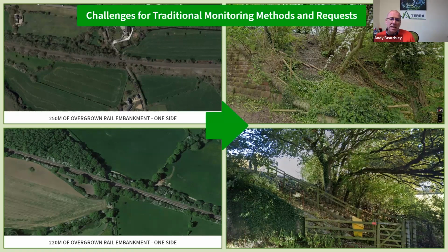In many situations, both installation and remeasure need nighttime track access, IRATA staff, safety staff, etc., causing a large total budget cost. Third-party land access can often be required to get the survey control outside of the area of slope stability influence, and that can be a challenging problem, even if it is possible. Wooden pegs or markers may be unstable immediately after installation. Repeated devegetation may be required, as lines of sight are often affected by seasonal vegetation growth. And then finally, extreme weather can affect the accuracy of traditional monitoring or even cancel shifts due to wet survey equipment.